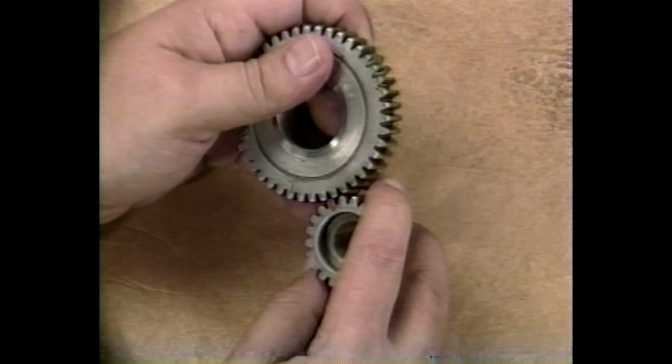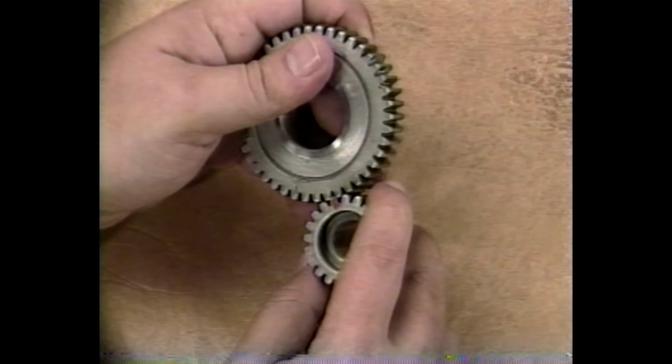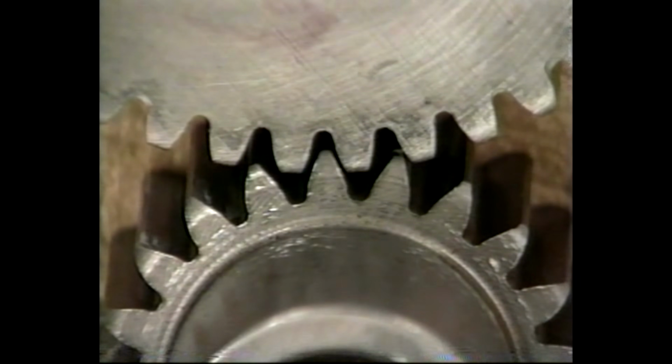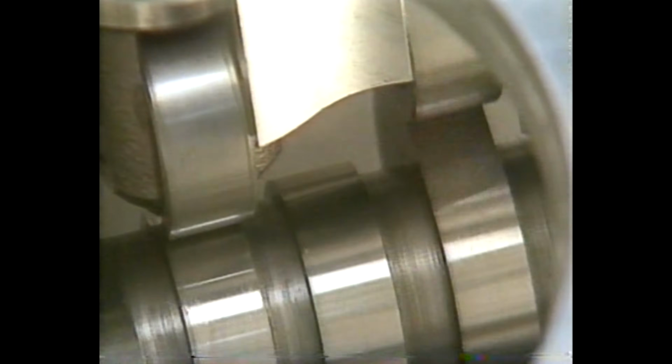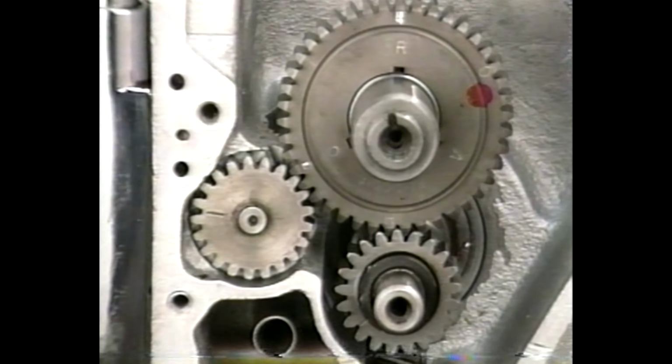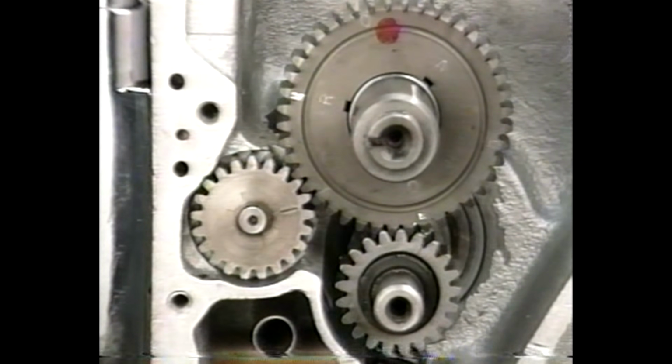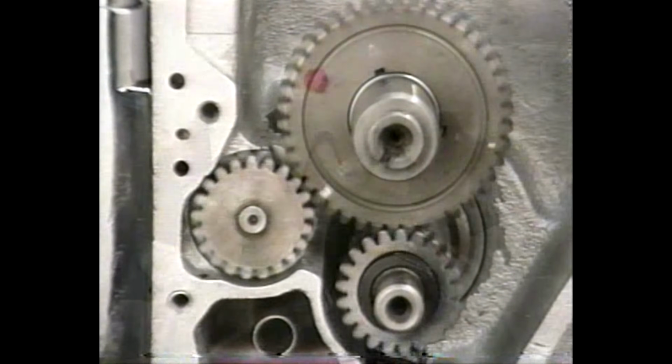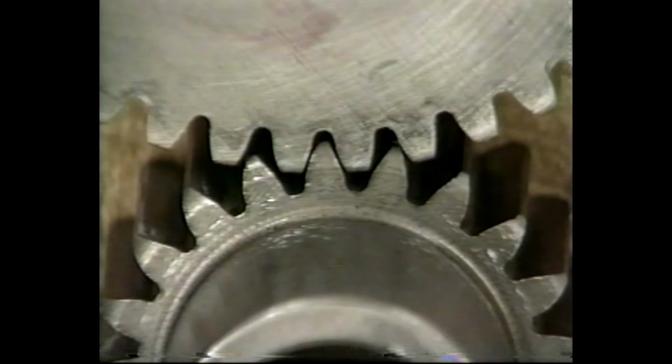If we have more than 0.002 of an inch of backlash in our gear train, the directional change of the cam drive gear will result in an audible click. This cam gear noise can easily be mistaken for a bad lifter roller or a collapsed lifter. However, no real damage will result, even where there is excessive noise. We have found 0.002 to be the minimum amount of backlash that will prevent individual gear tooth overloads.